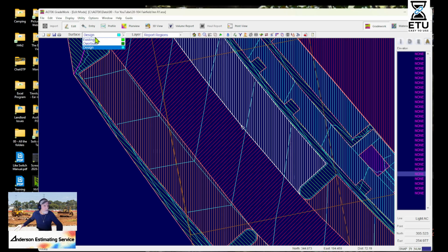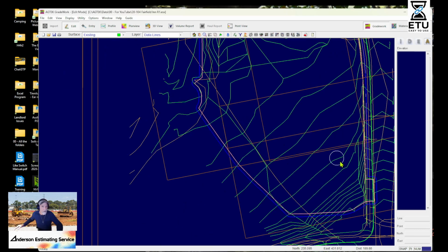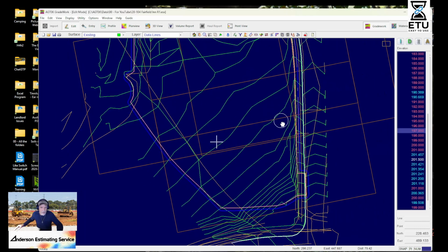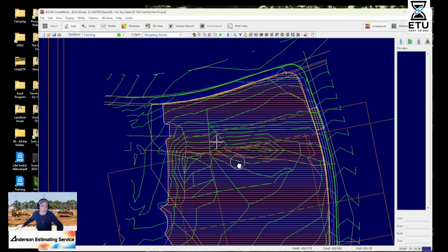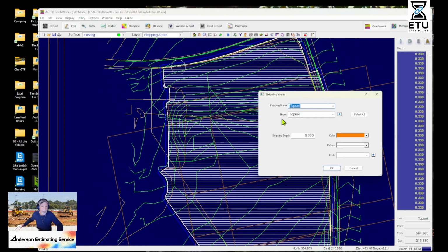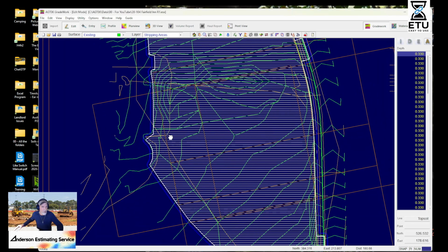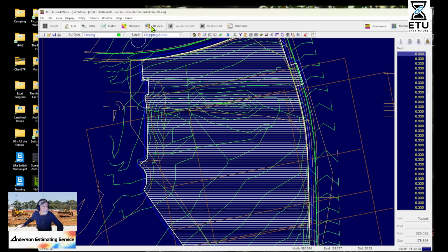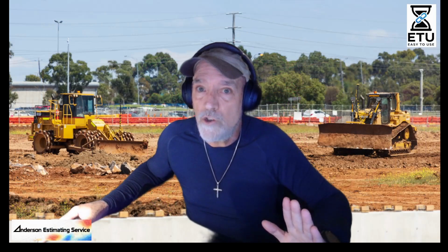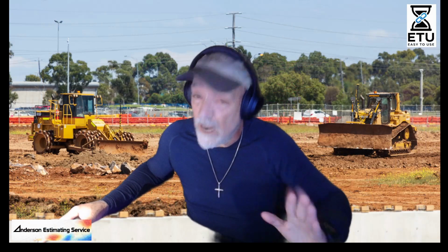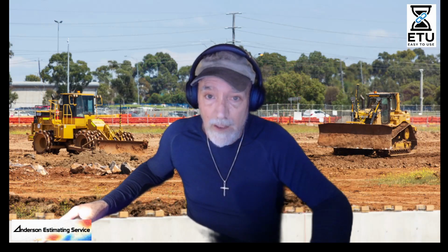And then in the existing, let's see if we have anything on this one. I don't see any stripping. Let's see, strip regions. No, it's just one big strip region. Let's see what it had. Topsoil. So this one had 4 inches of topsoil. So we stripped this whole site, 4 inches, okay? And then we compare that to the design stripped, okay? That's the quantities you should be comparing. That's how you get your volumes, okay?